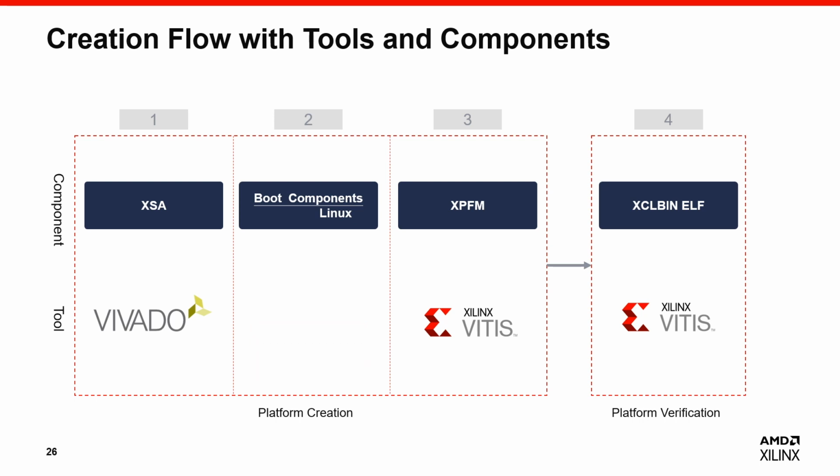As we know, except for the device tree, which is strongly hardware related, all the other software components are generic and reusable for other devices with the same chip series. So, we extract the images which are generic and reusable, such as the kernel image, boot images, and sysroot, into a common image package.